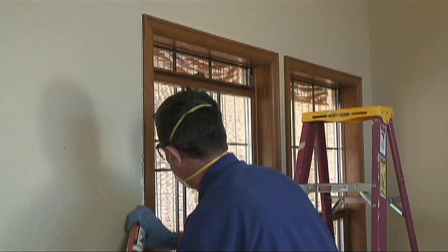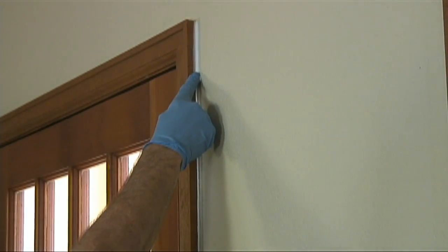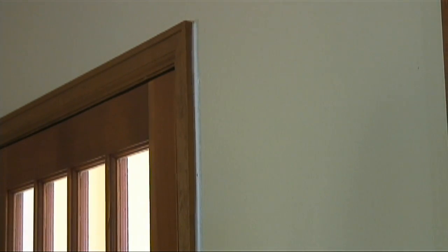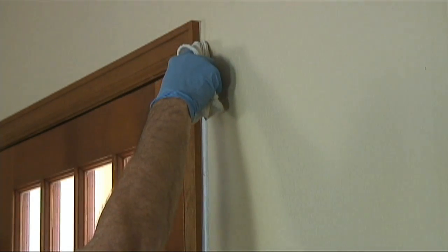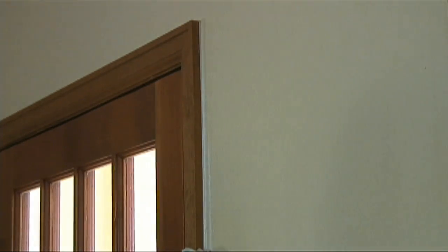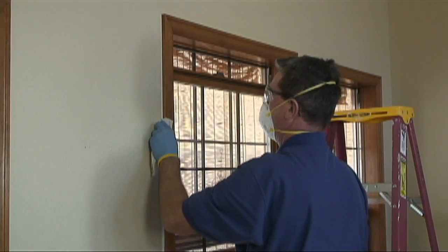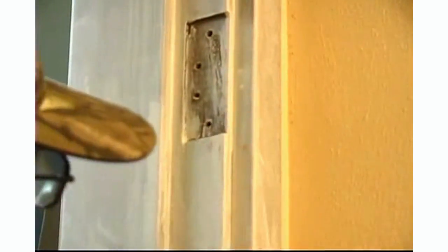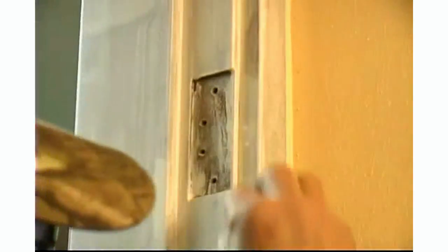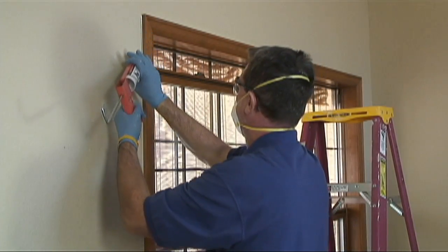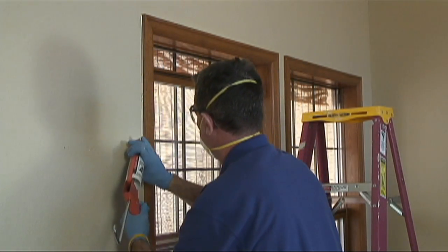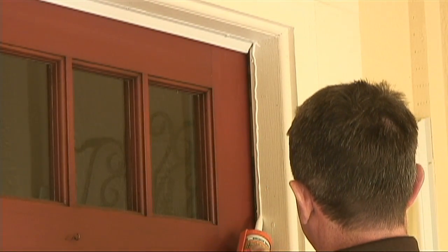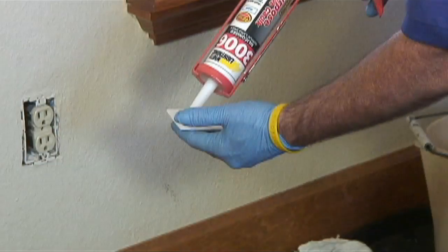We recommend wearing nitrile gloves when caulking and press the caulk into the gap using the tip of your index finger. Immediately after running a bead line of caulk, use your index finger inside a clean, damp cloth to clean the area you have just caulked. Lightly wipe over the areas you have already caulked to clean any excess caulk and provide a more uniform look to your caulk installation. Continue this process around all your windows, doors, and other areas inside your home that need to have the gaps and cracks air sealed.